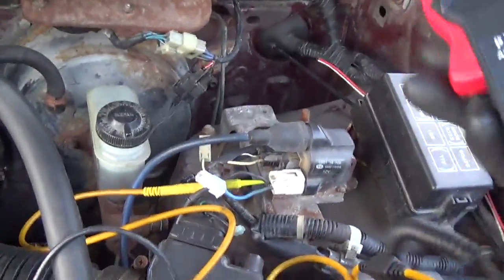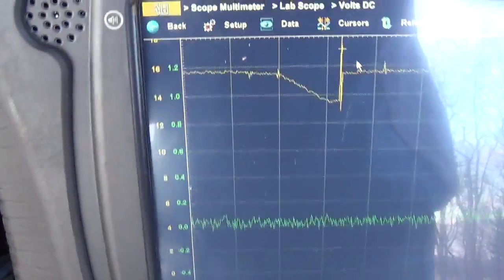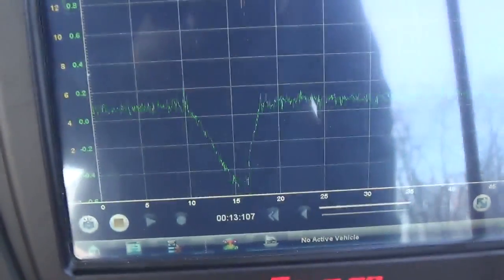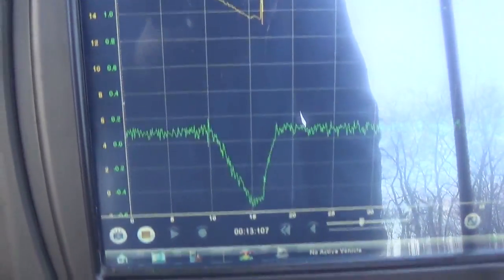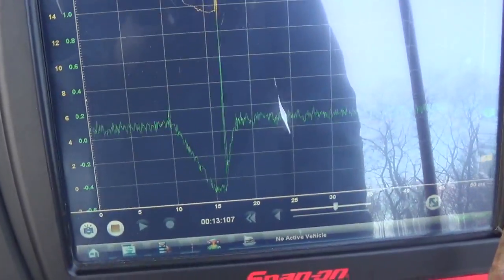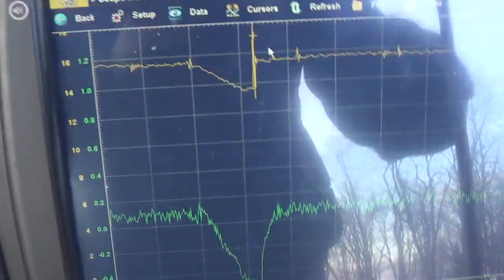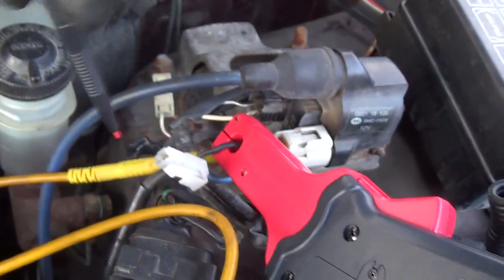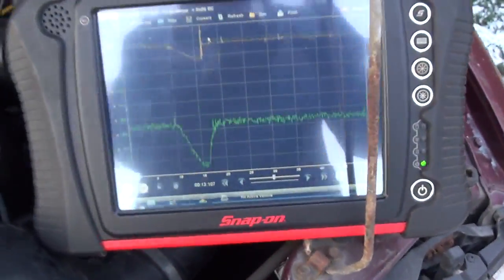well, let's see, I have it re-zeroed. Press the 0 button, we're at 0 amps, put it on this black wire, and check that out. We have like a half an amp, negative half an amp, so the current would be going back into, supposedly from the ICM, back into our feed. Now, that was very strange.